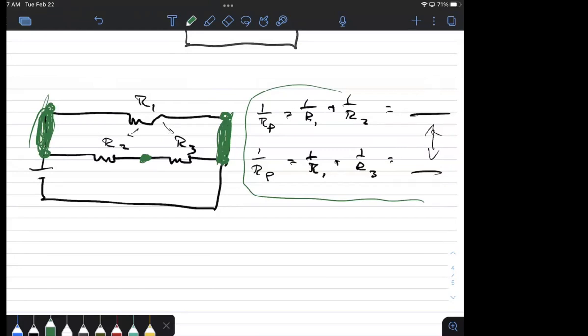But when you get this question, which is kind of unique, it looks like R1 and R2 should be in series since they share one node in common. But of course, we know it's not in series. And how do I know? Well, I have to use the other method, which is the logical one, follow the current and see what's happening there. So for me, what I would say as advice is, given something like this, do the simplest things you can do first. And when I see this, this is the simplest thing sitting there. Two resistors in series, add them together and replace them.